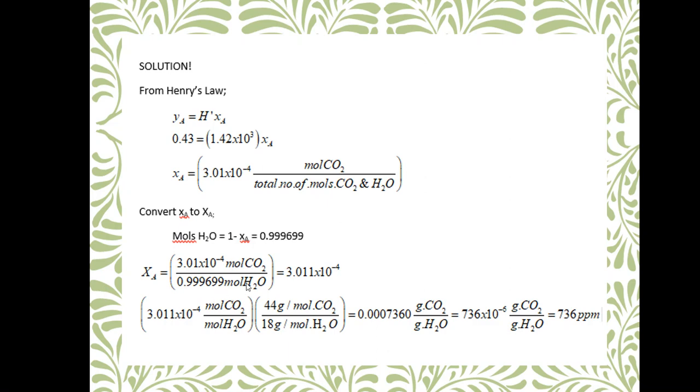So look at the unit specifically. The numerator is mole CO2. The denominator is mole water. So it's not mole fraction anymore, but rather mole ratio. So I have now the mole ratio. Why convert into mole ratio? Because I want to convert the moles here into mass units.